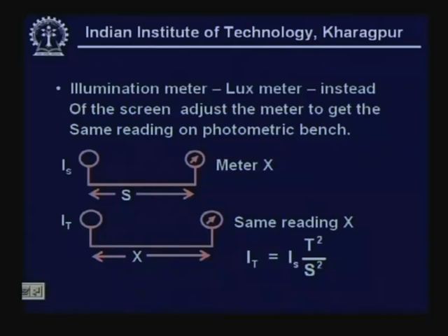Then the next stage, we take the test lamp, we replace the standard lamp by the test lamp and then vary the position of the lux meter to obtain the same reading of illuminance.